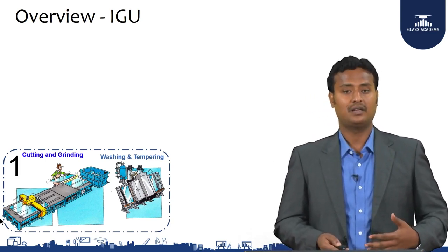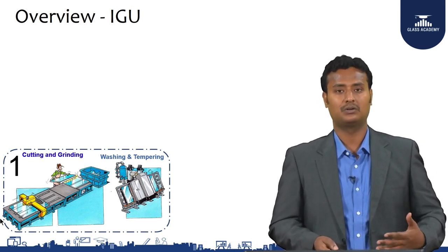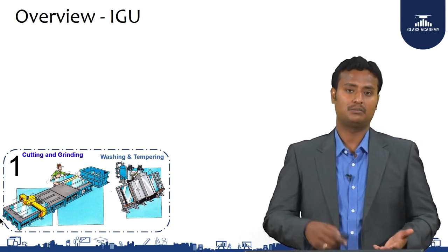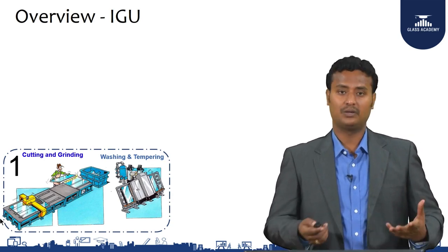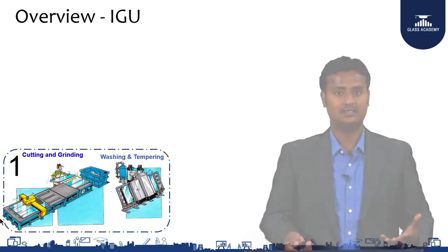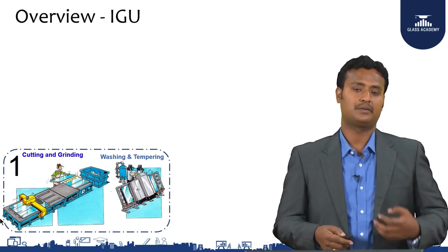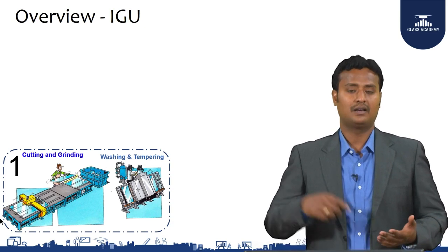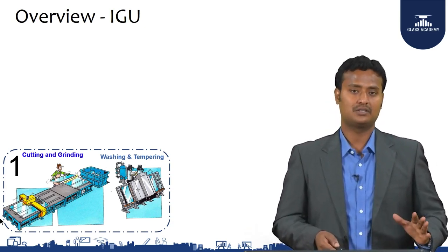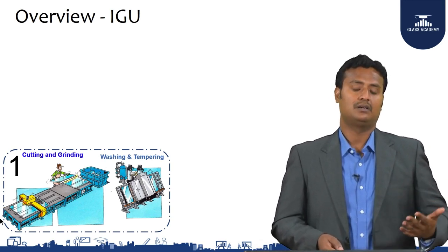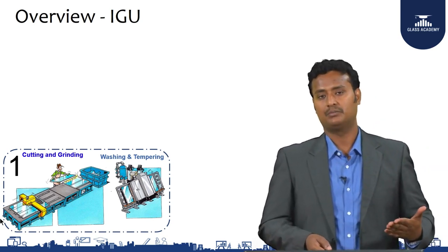And drying is most important. If any water droplet is present on the Low-E or the normal glasses and you feed it into the furnace, it will break. And even if it does not break, with Low-E glass or any other glass like ceramic glass, the coating burns because of the water droplets present on the coated surface. It will have an effect after tempering. So washing is the most precise process in terms of IGU, because it enables you to see and do a thorough quality check before taking it to the tempering.